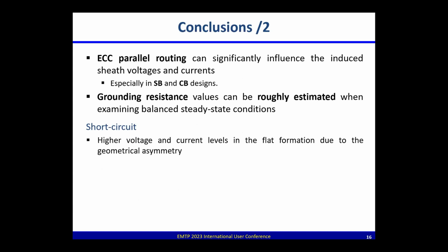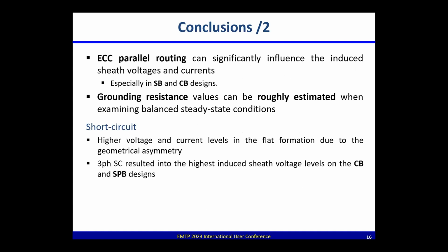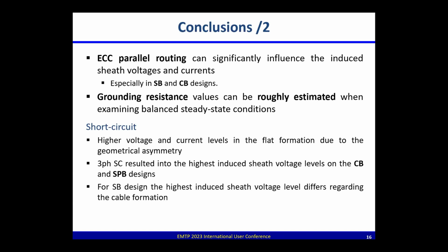And in short circuits, we get higher voltage and current levels in the flat formation due to the geometrical asymmetry. And for the single-phase and three-phase short circuit cases, the results we got are higher for the cross bonding and the single point bonding designs. And for the solid bond design, the highest induced sheath voltage level differs regarding the cable formation. And I have added one extra slide, but I forgot.